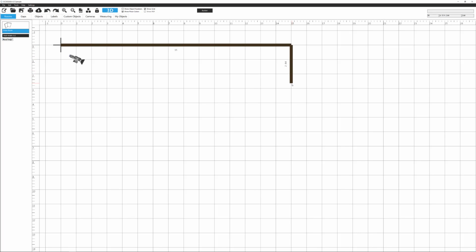And when I drag the second wall here, you'll see that the wall will try and snap to the grid, which in this case is 1 meter. But if you hold down the shift button, you can move it freely. But I would like to have the grid snapping, so I'm going to let that go. Left mouse click, add another wall, left mouse click, and move.